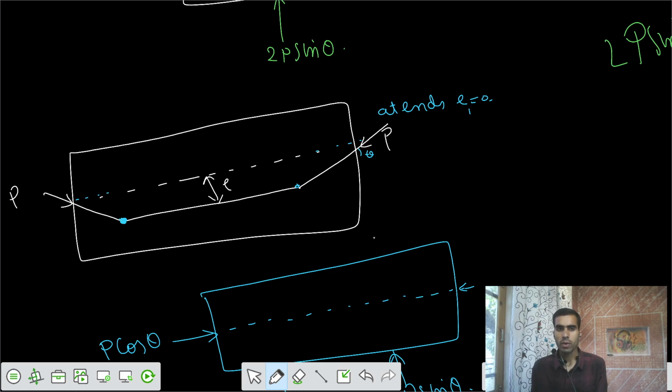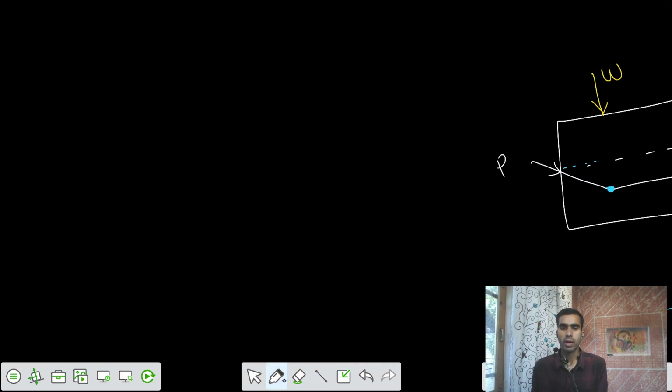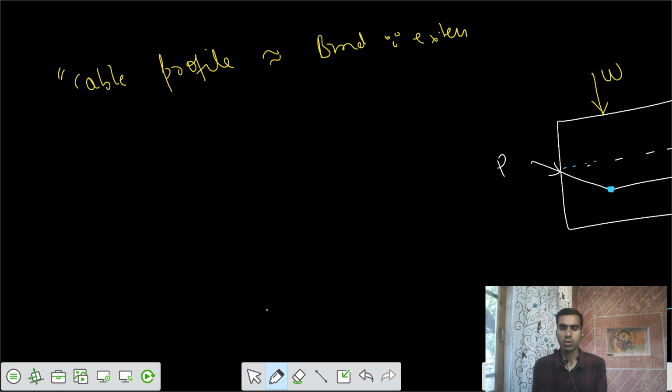There might be some external loads also. This cable we are providing corresponding to vertical loads. If there was a vertical load here, and one more vertical load here, W1, W2, that was your external point load. That's why we have provided the cable in the form of the BMD. The cable profile is similar to that of a BMD because of external loads.